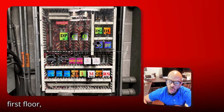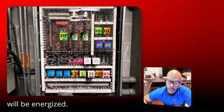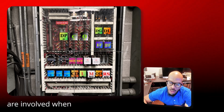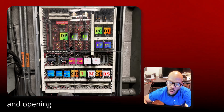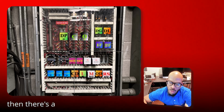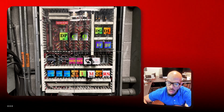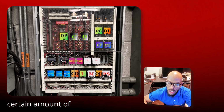On the first floor, this relay will be energized, and on the fourth floor, this one will be energized. These two right here are safety circuits. When you click these, they show the circuits that are involved when the doors are closing and opening. If something gets in between the doors, there's a sensor that can detect that, and it'll make the doors open back up. These are timer relays that help the motor run a certain amount of time.